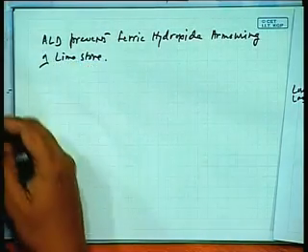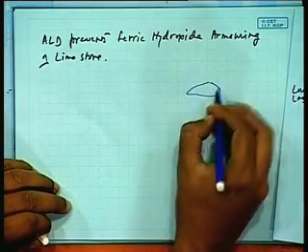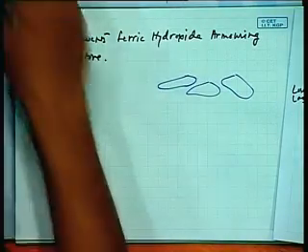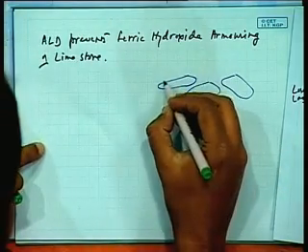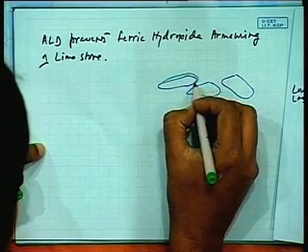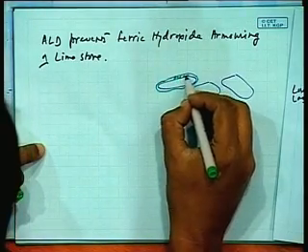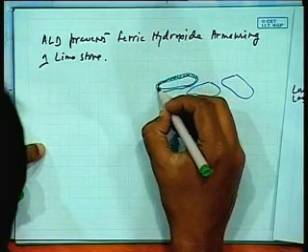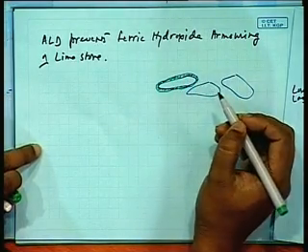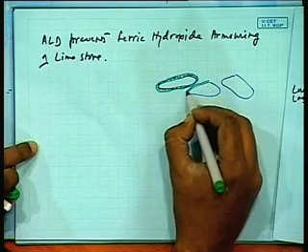Say, in all the particles of limestone chips present there, the ferric hydroxide would deposit on top of them. As a result, there would be less surface area exposed for the limestone to activate.